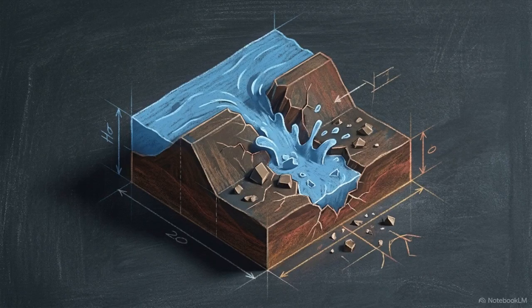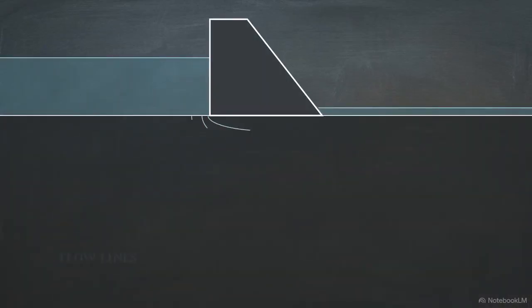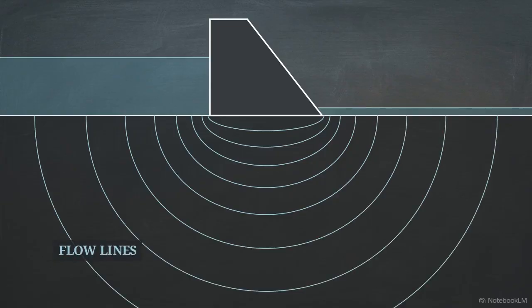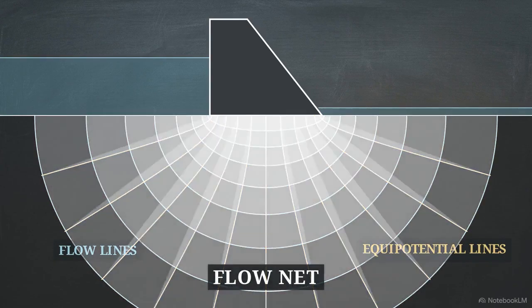To prevent catastrophic washouts, engineers have to precisely quantify this seepage volume. Calculating this entirely through abstract differential calculus is difficult, especially when the site boundaries are complicated. We need a way to physically map the geometry of this groundwater flow, because if we miscalculate it, even the strongest surface structure will inevitably collapse. The solution is a geometric tool known as a flow net, representing steady-state fluid flow.